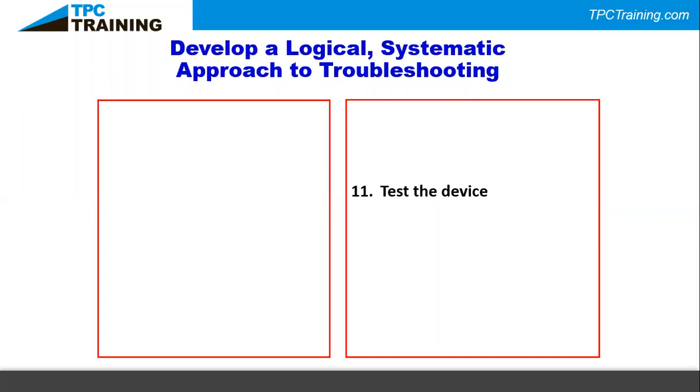So in the electrical case, right, you can test with ohms of resistance and test across that device and make sure it gets what the manufacturer specification is for that device across either a contact or that coil.